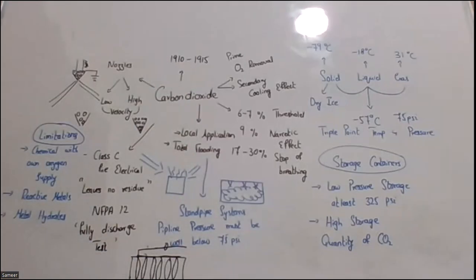And if the weight is less... but the weight also does not give us a confirmation. One thing you should always remember: the weight itself sometimes does not confirm that the carbon dioxide is in good form, because if the carbon dioxide has already converted to a solid form, we may still get a weight of approximately 5 kg only.